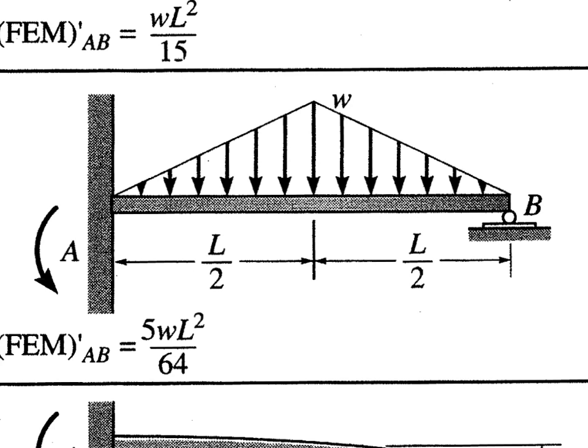It's like a surface. It's like a normal force. The bridge is sitting on a ledge. Why don't I have to worry about it moving up? Because what pulls down? Gravity. Gravity pulls down. So this bridge is not going to suddenly lift off the ground and start floating above the ground. It's naturally going to push down. So this roller support prevents vertical motion, specifically in the negative direction. Again, it prevents the end of the diving board from actually bending. If you jumped on a diving board, it would sit there and bend. If you did it with this bridge, it wouldn't, because it's being supported at the end.